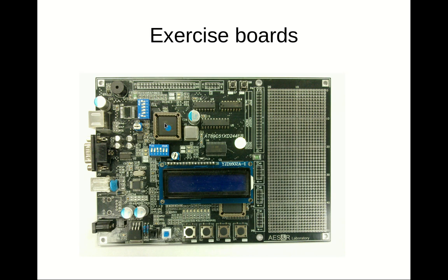This microprocessor is initially designed to communicate with UART RS232. So what is necessary is basically a translation chip that translates the USB signals to UART and there to the RS232 standard.